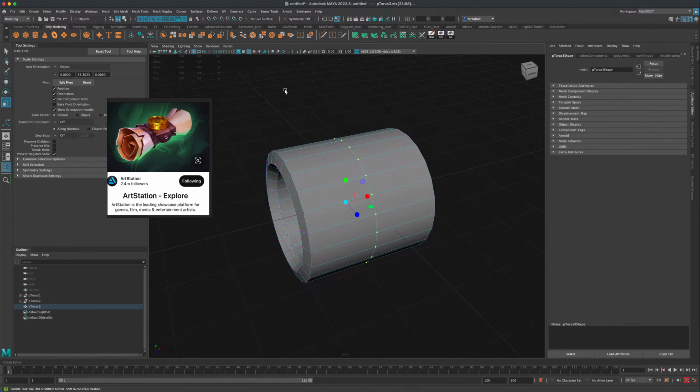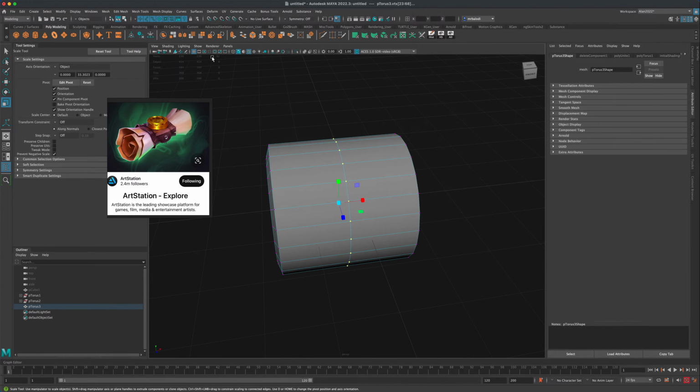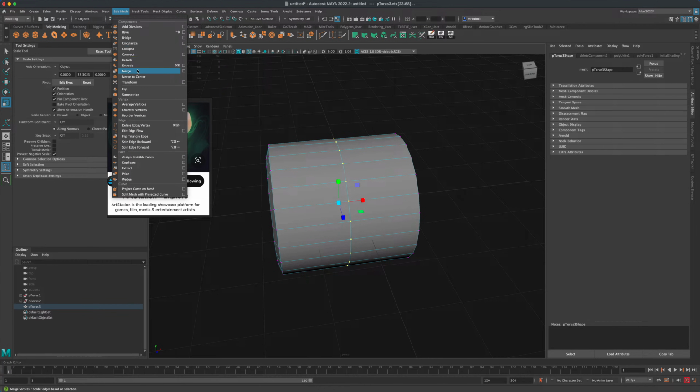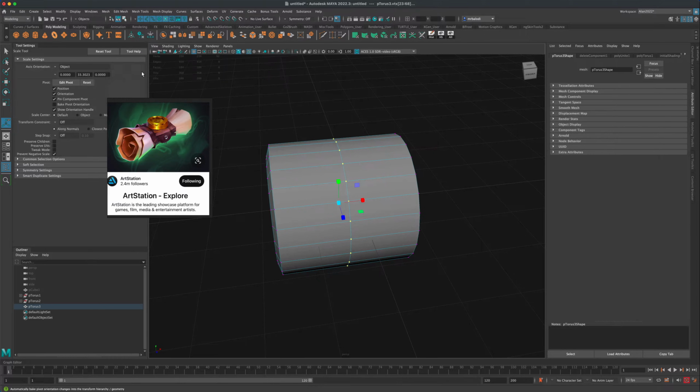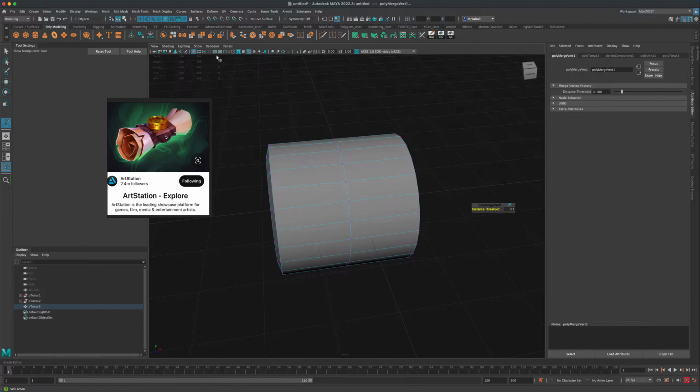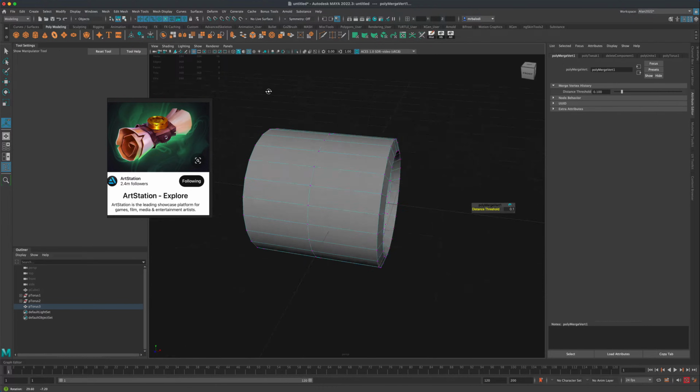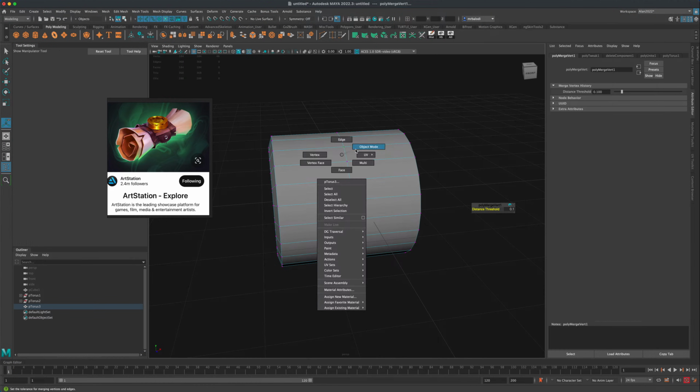So in my case, I have 92 verts selected right now. And I know that if I go to Edit Mesh and merge, that 92 is going to change, right? It's going to half. So 46? I'm going to click on it, and sure enough, they merged, and now they're 46. So essentially, I welded them together, right? And that's great.